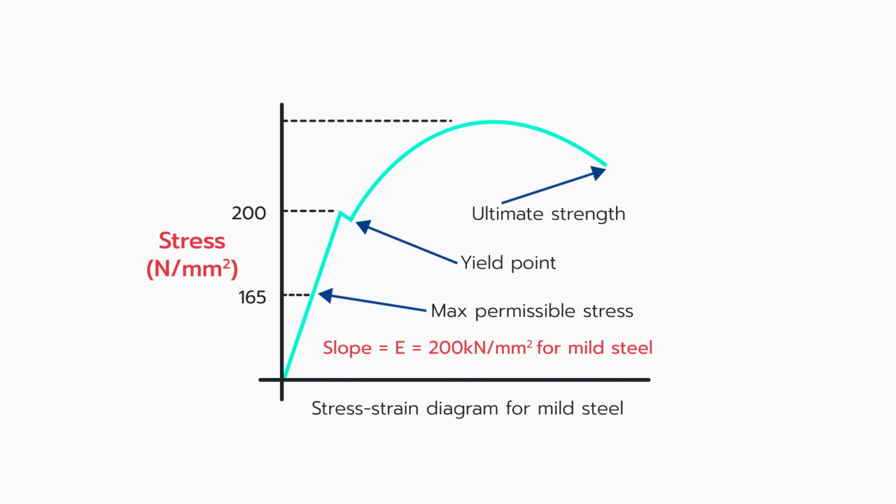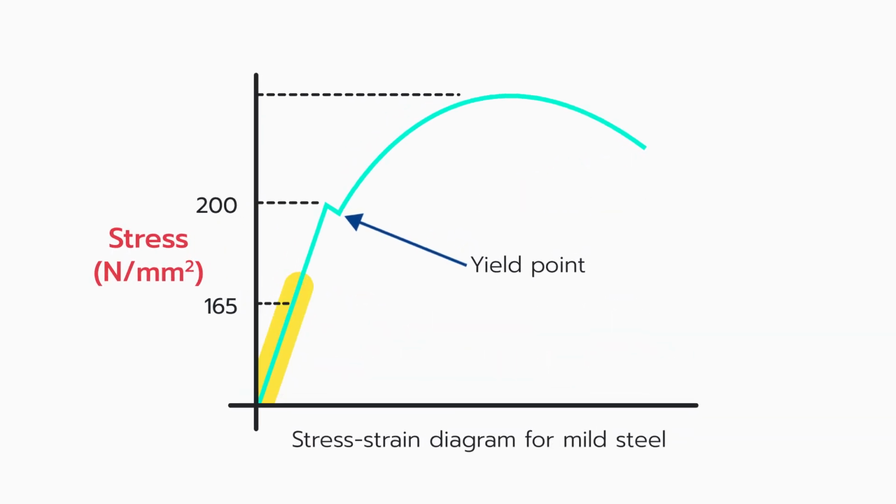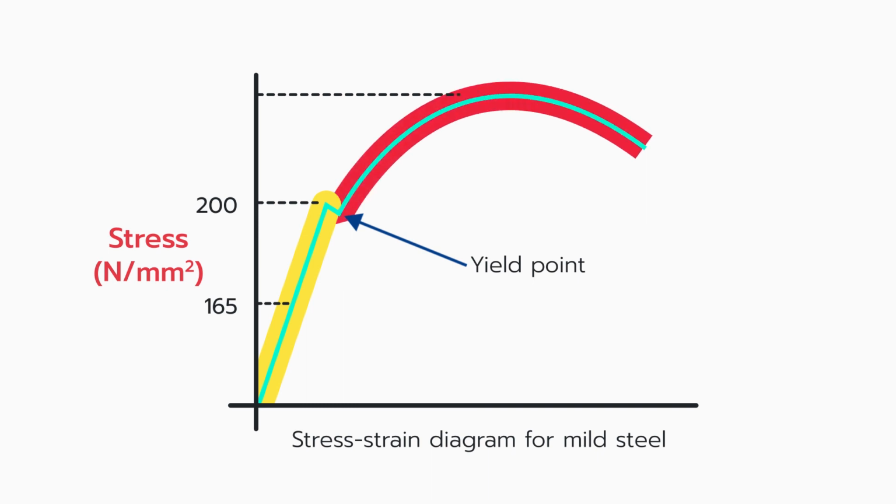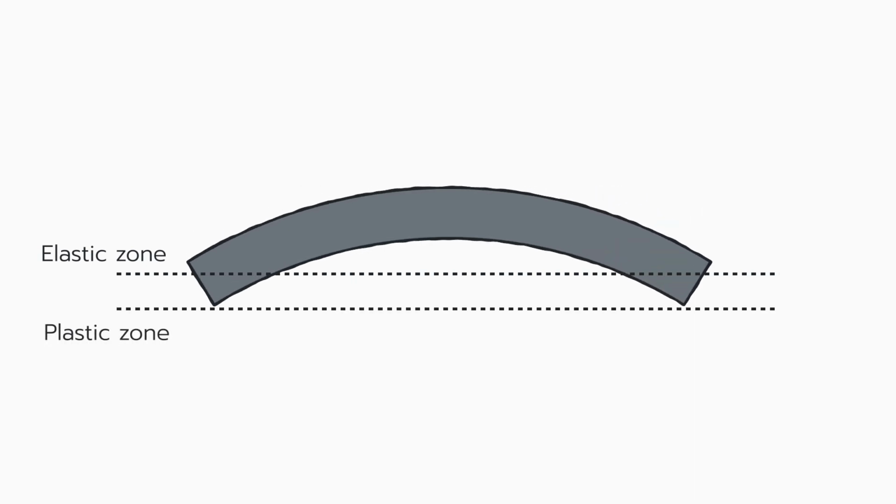These stresses can be calculated with a high degree of accuracy. Hence, we can predict a structural member's performance if we compare the stresses that it can take before it reaches its yield point, compared to the actual stresses it will be subject to once all the loads have been calculated. A material can still perform after yield stress. Once material is past the yield stress point, it is in the elastic zone, then it is in the plastic zone. Materials return to their original length when stressed in elastic zone, but deform once stressed past yield stress point.